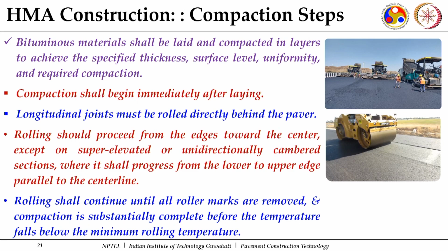Once you have laid it, the paver itself gives a good amount of compaction, because these paver screeds have a vibrating arrangement as well as a tamping arrangement. So they do a good amount of tamping, and the vibratory arrangements are there.